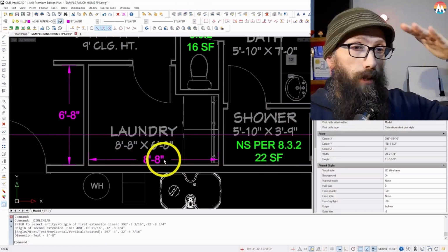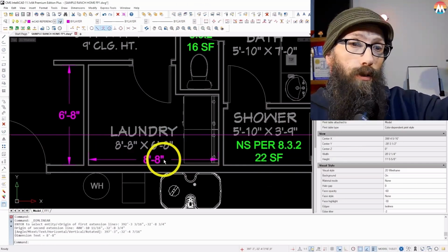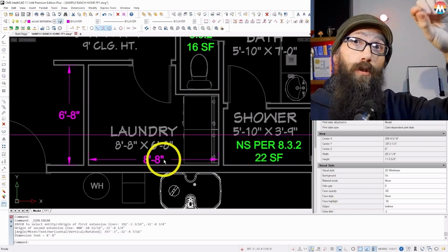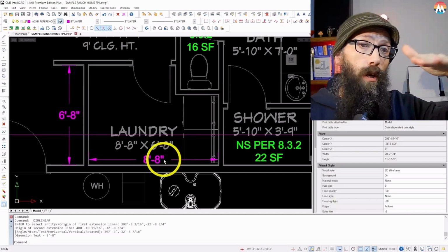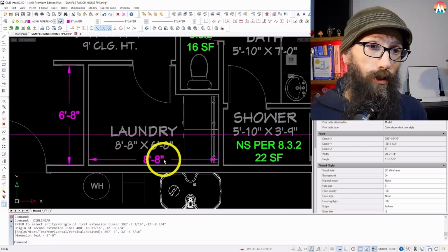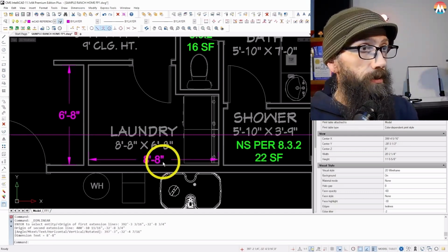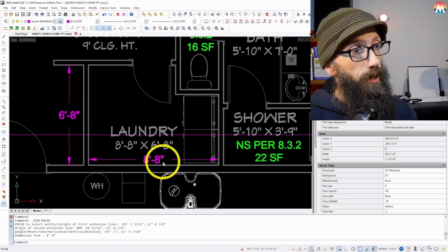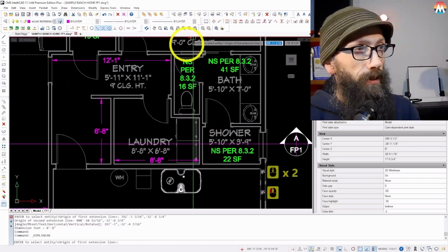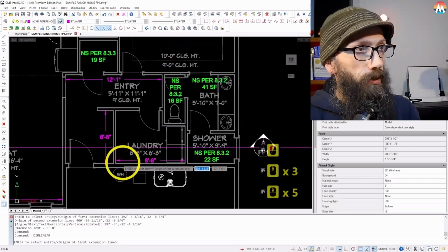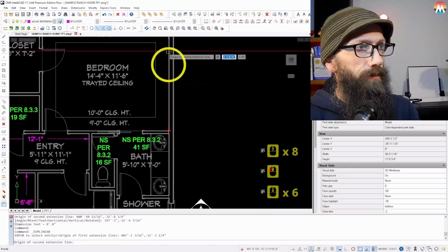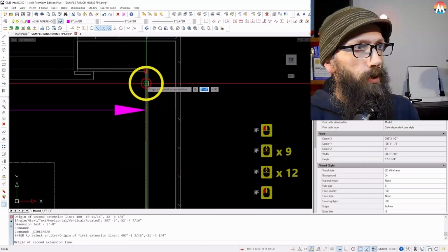if you look at the spray pattern of the sprinkler, it's spraying onto the walls, and you can see the arc of the circle high up on the wall, close to where the wall meets the ceiling. And so there is a circle, but it's an incredibly large circle. In fact, it's much larger than the square that we're designing to. But that circle is taken into consideration. We've had jurisdictions that are confused and thought we needed to add sprinklers into the corners. But, you know, everybody's got to start somewhere with their knowledge.